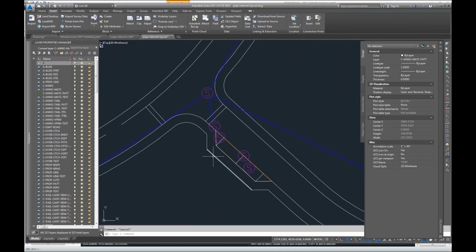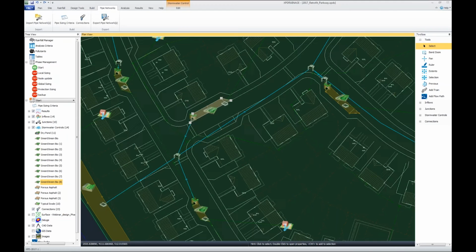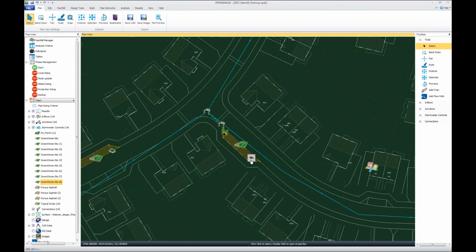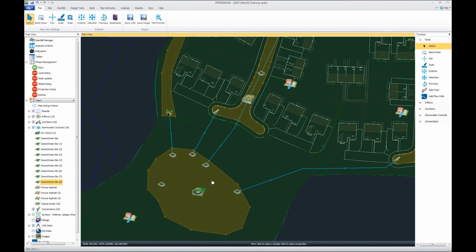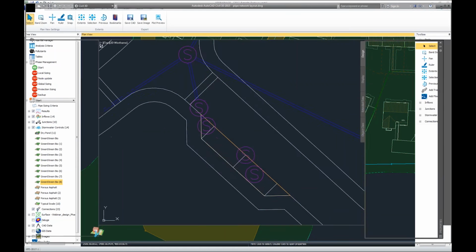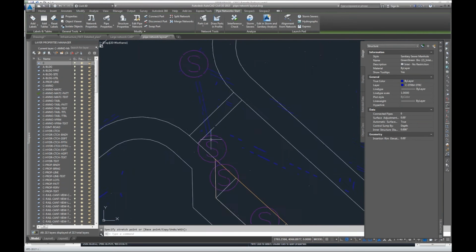So what we have done, instead of just bringing in pipes and manholes, well, here's a facility, here's a rain garden. If I go back to our software, we truly show this inlet location. Same with the pond down here. We are actually going to show where things daylight out. I think that's hugely important. XPDRAINAGE is showing how it will be built. Okay, let's go back into the software here. So we're going to bring these in as markers into Civil 3D. I could change the location of the inlet to be more precise, more specific. We're transmitting that here into Civil 3D.